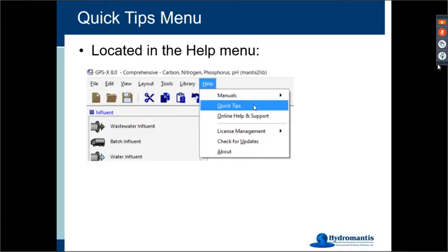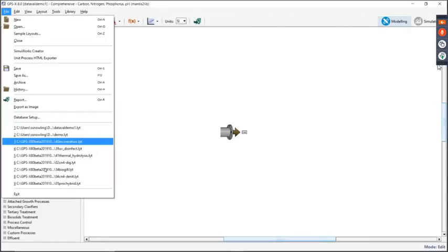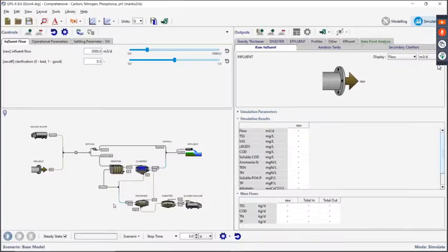So you'll load up any simulation that you want to be able to run. Here, I'm just going to run the steady state solution to this particular very simple model. And then once that's done, this button up here will become active, and then we can generate whatever kinds of reports that we like. So you can see here, here's our standard Word report. There's different options you can include or exclude certain things. I'm just going to generate it with the whole works. And it prompts you where you would like to save that. And then once it's done, we will open that and take a look.